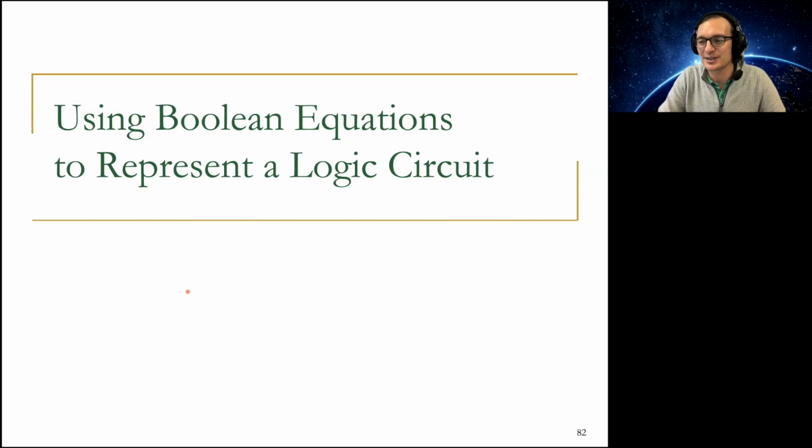So certainly, I'm not going to say no. People are trying to actually build circuits that are more reliable, so that if something happens to a transistor, your circuit still operates. But overall, yes, there are a bunch of different reliability issues. Wear out is one of them. It could be that your transistor gets affected by noise, some particles. It could be that there's crosstalk also between different transistors, between different wires, for example. They could get affected, similar to RowHammer, for example.